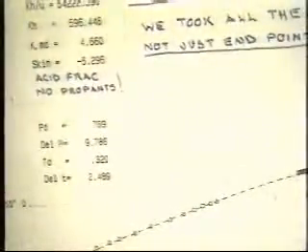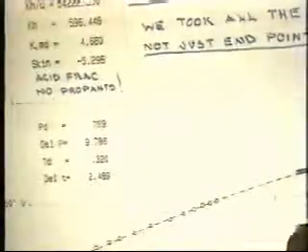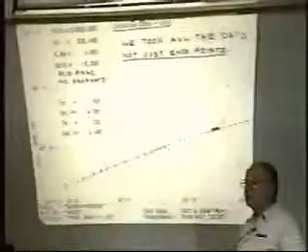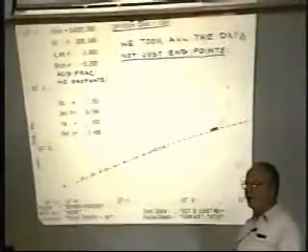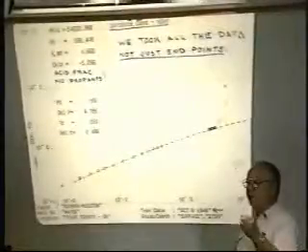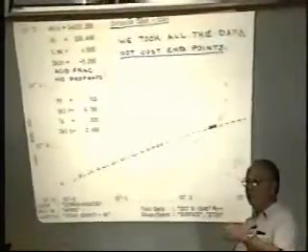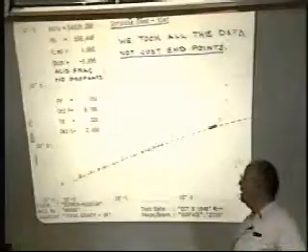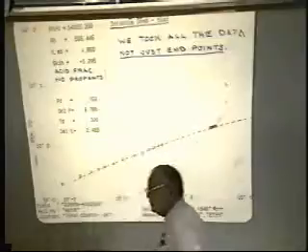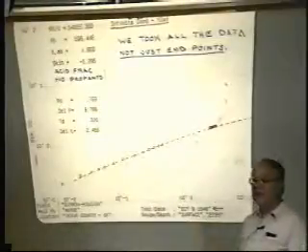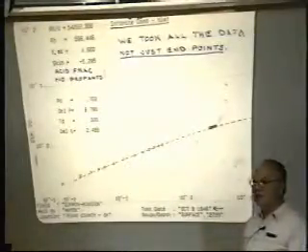To show you what 1945 data looks like: I see a lot of people badmouth, or who are not even aware of, multi-point tests, or say that they're no good. Part of the reason is a lot of people think that all you do is measure the flowing pressure at the end of a flow period and a rate, and you plot that data, and that's it. Well, in the gas department, what we did was measure pressures and rates every 15 minutes with a deadweight tester. Not with a gauge, but with a deadweight tester.